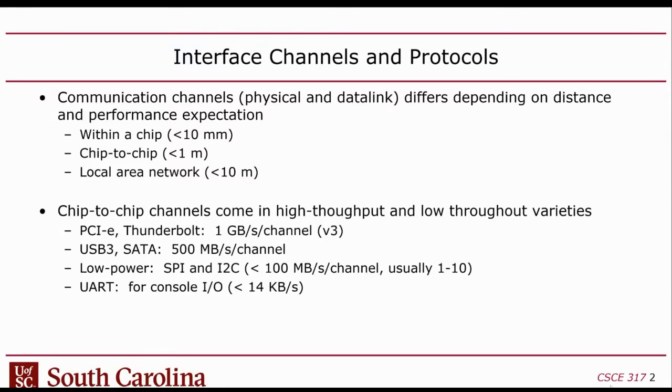So if you need to get a message across the channel fast, your best bet is to use these low power SPI and I2C links, because you don't have to go through DMA, basically. You don't have to send the data through a memory and then have the peripheral go and access that memory. That takes time; there's a latency.